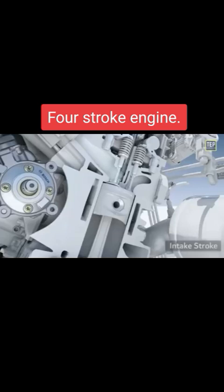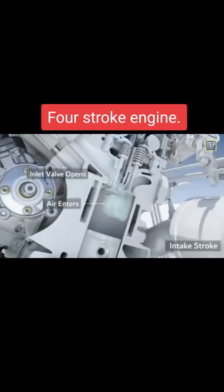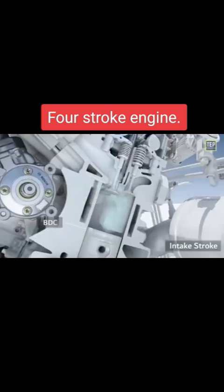Intake stroke. In the intake stroke, the piston moves down, the inlet valve is open, which allows air to enter the cylinder and fills the space. Then the piston reaches the bottom dead center and again starts moving up.